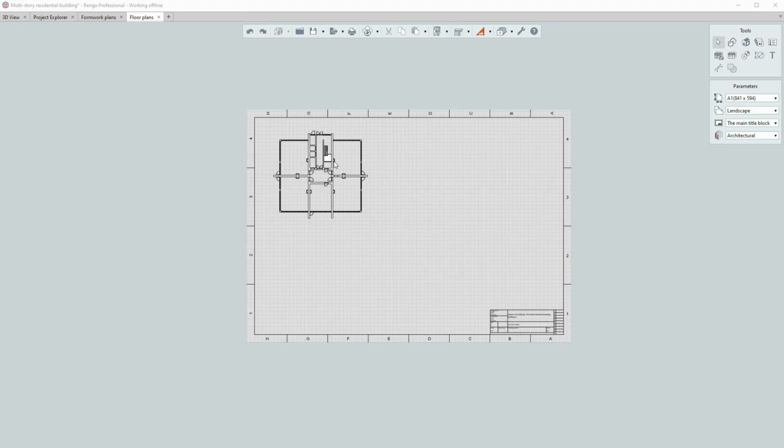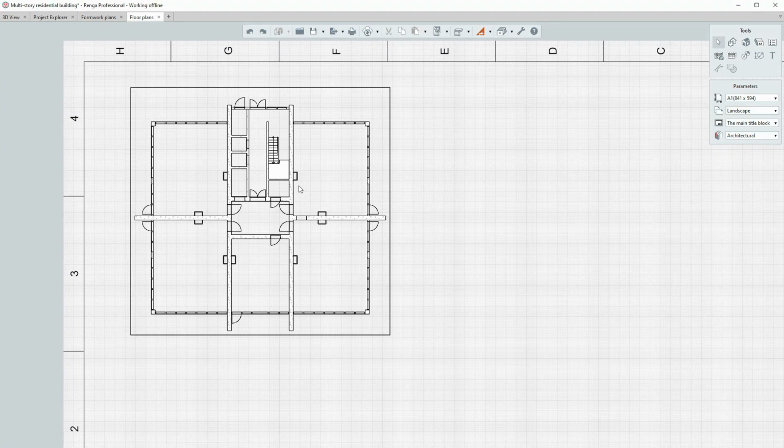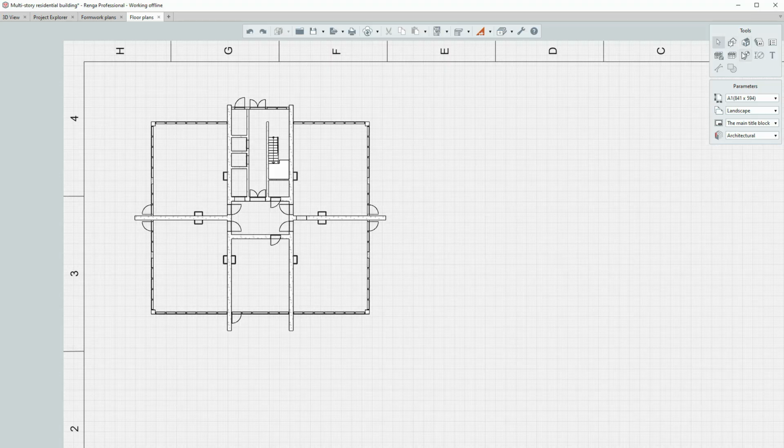In the next step, we'll add dimensions and axes to the drawing sheet. Designations in Renga are tools intended to create the following objects in the drawings: grid line, section, tag, and callout. All the snaps and accurate construction are available for designation construction. The grid line designation includes the following methods of constructing grid lines: automatically by view, line by specifying 2 points, arc by specifying 3 points, and arc by specifying start, center, end points.